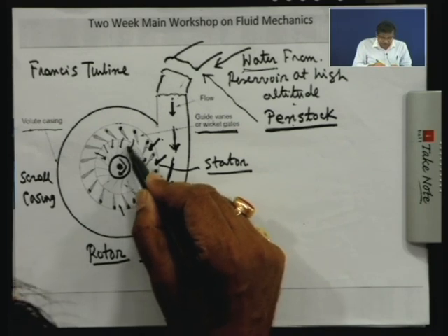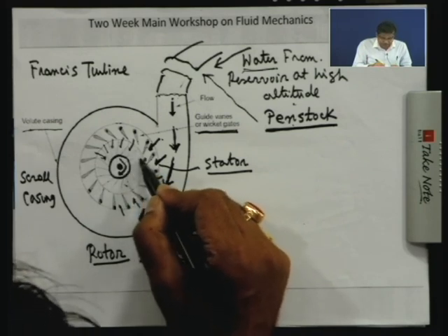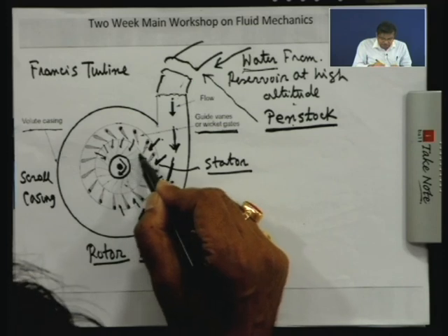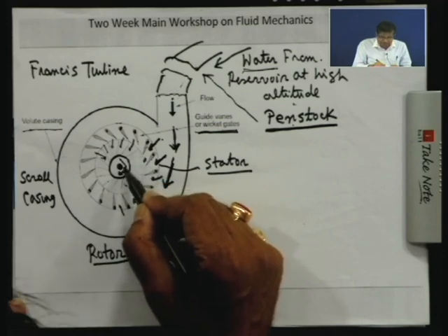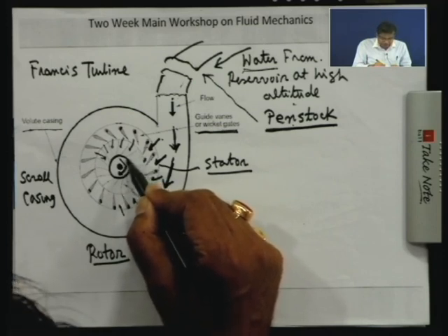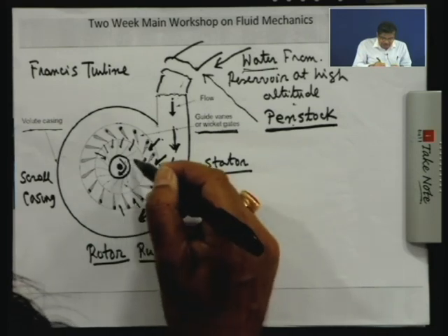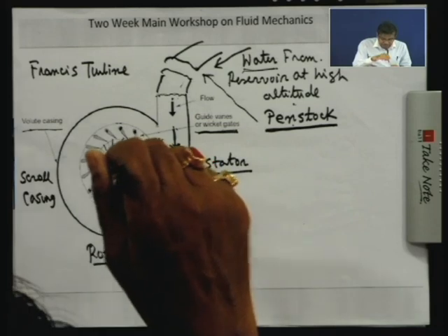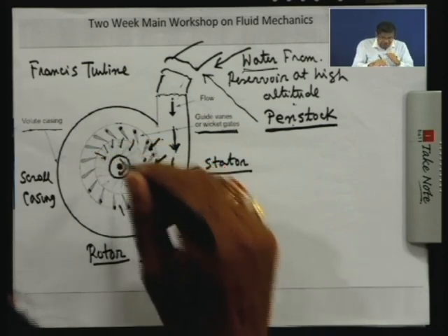This is the situation, as I have known that the relative velocity has to increase to decrease the pressure and to get the head delivered. Then finally, this comes here at the outlet, and then it is discharged, that means it is turned in the axial direction, that means in this direction, and then it is discharged.